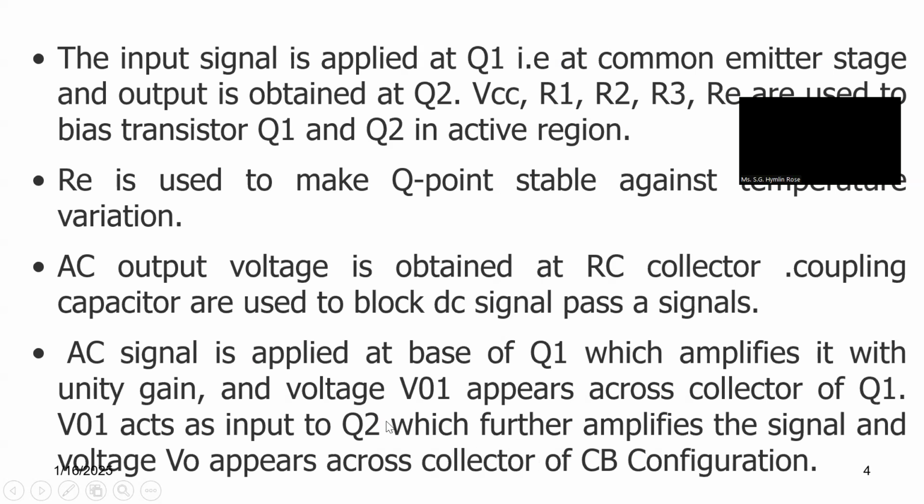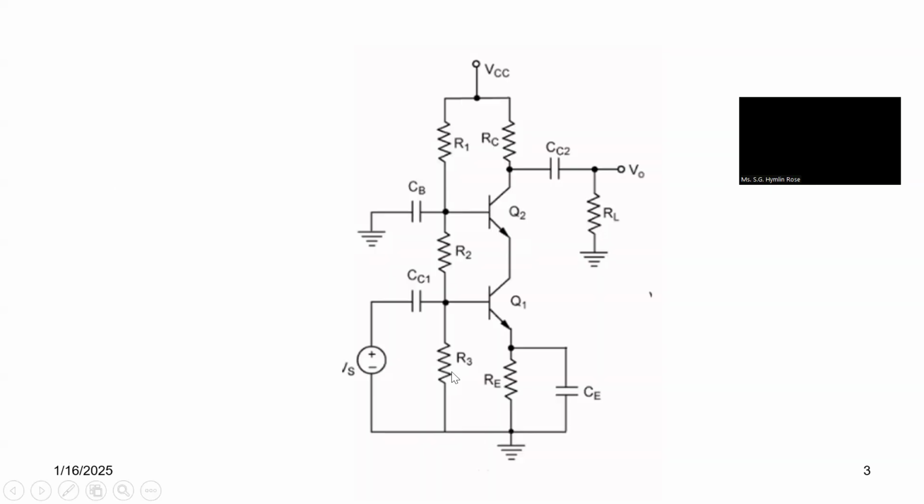So how it works: the common emitter first stage has high input resistance, and the second stage common base amplifier has a very low input resistance. So CE drives the CB for both AC and DC inputs. The lack of direct coupling from output to input eliminates the Miller effect, since there is no need of any capacitance between the output of Q1 and Q2.